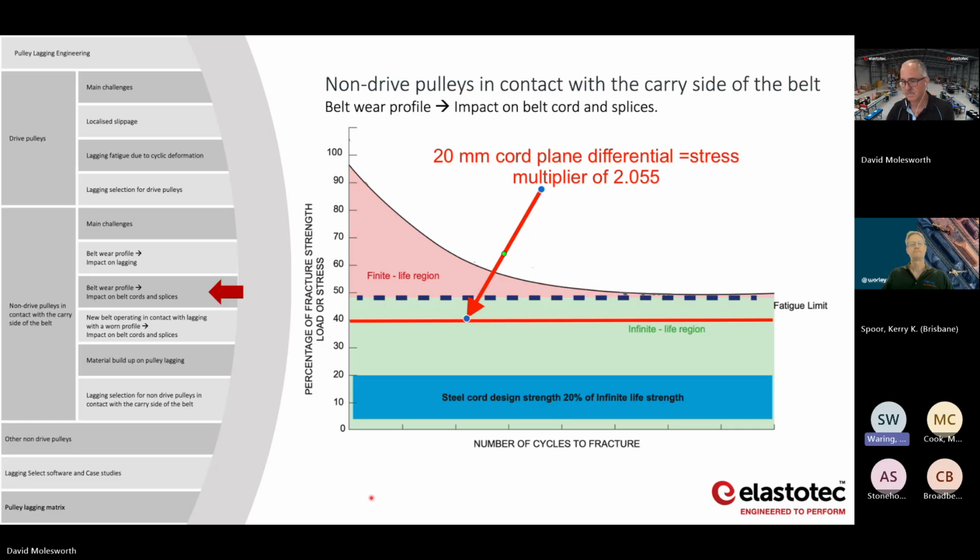Because Kerry, I wasn't sure if you actually have a transition length that exceeds the amount that you calculate, whether or not the idea is that if you do have that transition length, that differential tension across the belt is sort of back to zero by the time you get to that length, and it's maybe only there if people have shorter transition lengths than they should. Yeah, I think that's how the calcs work. I didn't go back and read it all again, if anyone else has done that more recently and remembers.